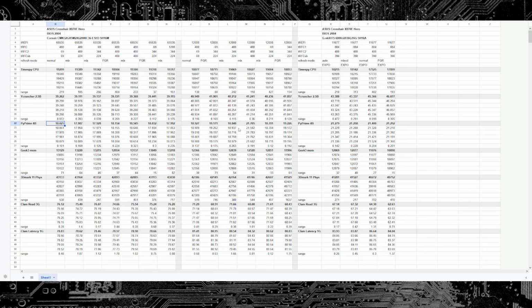So, that's it for the video. Hopefully you find this somewhat useful. Obviously, I'm going to be doing more testing on this because now I'm very interested in just how low you can push TRFC same bank on more relevant memory chips that aren't 16 gigabit MDI, because that's obviously the deciding factor for whether you should use mixed mode or normal mode. And if it turns out that basically only MDI does TRFC same bank so low that it's actually viable, then you can just stick to normal mode.